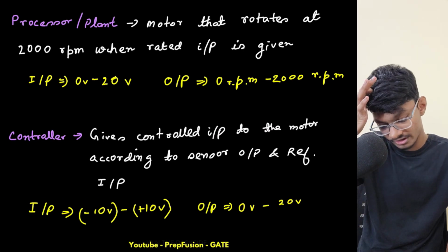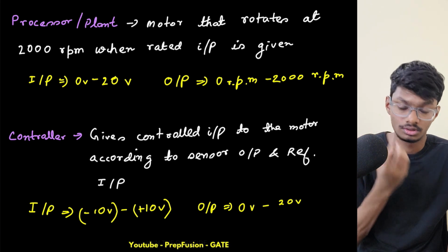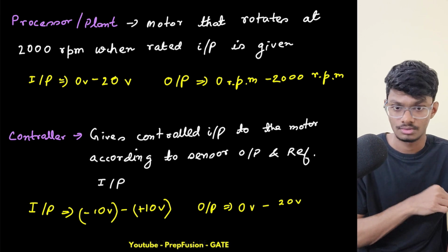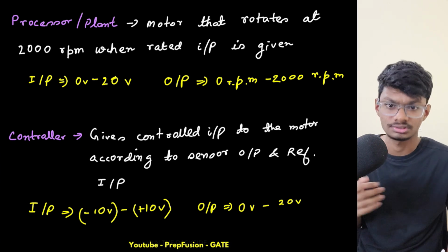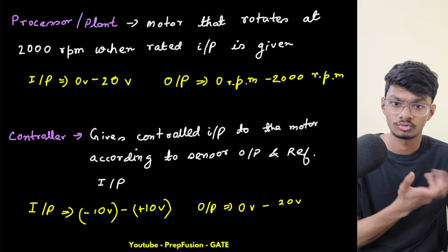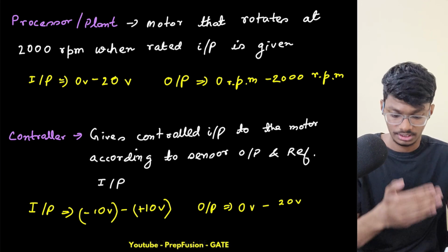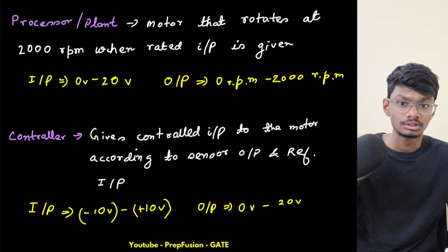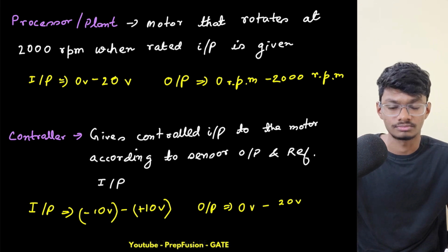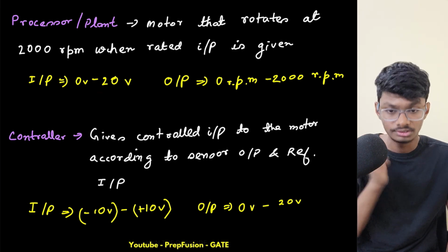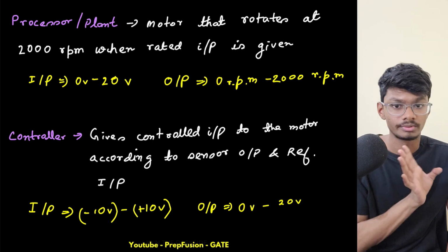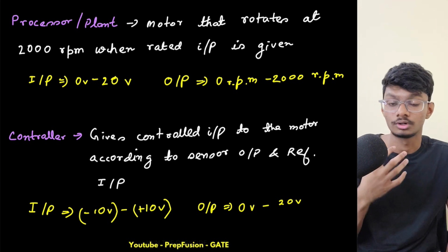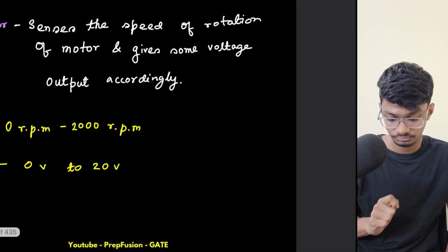Let's say my motor input is 10 volts, and it is not giving me 1000 rpm, it is giving me 990 rpm. That may happen. Motor has non-idealities, motor has losses. The electrical people will relate: motor has copper losses, motor has core losses. Say I just bought the system today, and one year after I'm using it, there may be dust in the system, and many other things due to which it will not give me proper output for some input, or the sensor is not able to sense the proper input. So due to these things, the non-idealities may come.